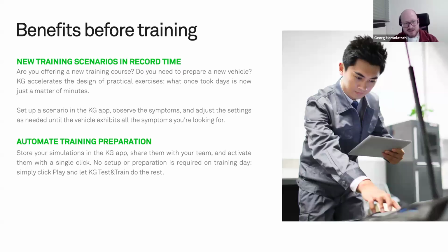With technology, this process from idea to final scenario that I can use with my students becomes a matter of minutes instead of days. So you can have an idea, you looked at the wiring diagram, have an idea of a fault that you want to run, then you configure that in the KG app, in the software, run the fault on the vehicle, and then see how the vehicle reacts. And if you don't have all the symptoms that you need for your students, well, then you can readjust.